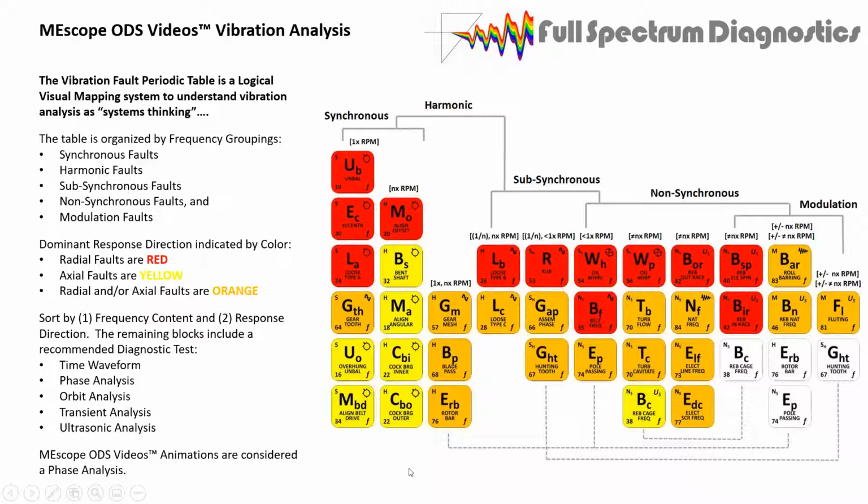And if you want to go in and do a phase analysis, you're checking all the different things across the coupling: misalignment, cocked bearings, mechanical looseness, bent shafts, belt drive misalignment, unbalance, eccentricity. Everything that's phase related is right there, and then natural frequencies as well.